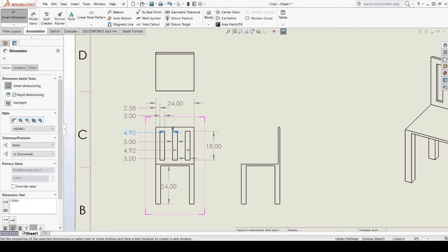And like I said, if they can figure it out from the other things that you have from a given reference side, then you don't need to. So for example, I don't need to put how big this width is, because they can figure that out. But for the most part, you want to have pretty much everything referenced.